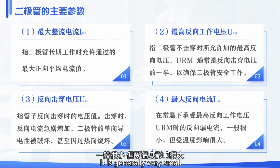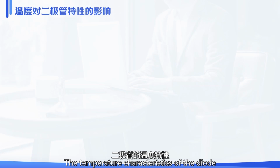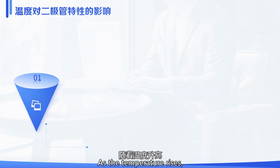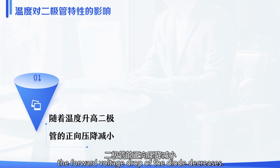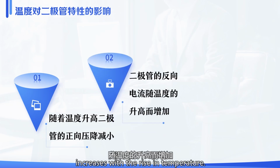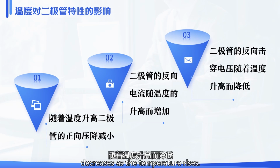It is generally very small, but greatly affected by temperature. The temperature characteristics of the diode are not favorable for the stability of the circuit. As the temperature rises, the forward voltage drop of the diode decreases. The reverse current of the diode increases with the rise in temperature. The reverse breakdown voltage of the diode decreases as the temperature rises.